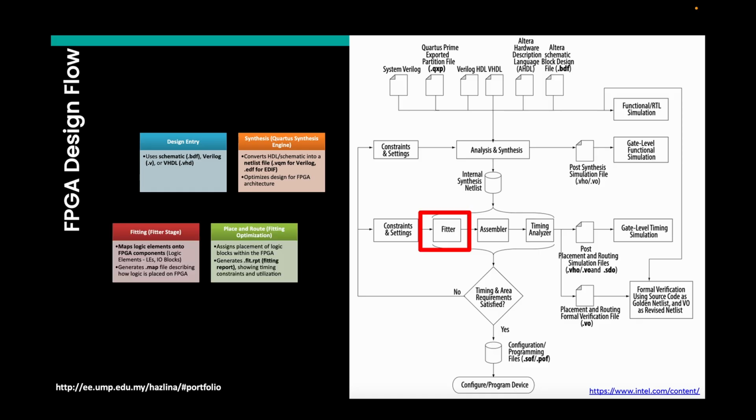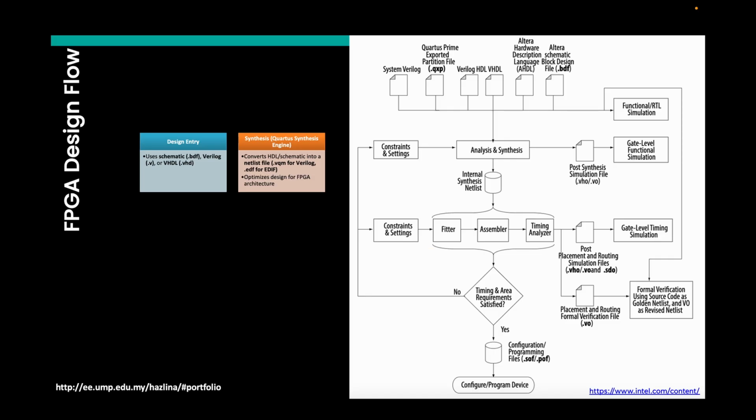Once the RTL design is complete, we need to verify its functionality using simulation tools like ModelSim or Quartus software. For example, before deploying sensor processing logic on an FPGA, we simulate its behavior to check for errors. This step helps catch logic flaws early before moving forward.